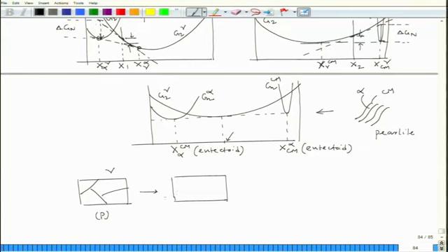Rather, it will form, first it will form along the grain corners or triple point junction. So, here the first nuclei of alpha would appear, and then they will start growing, and in the meantime alpha can also appear on the grain boundary, grain edges,